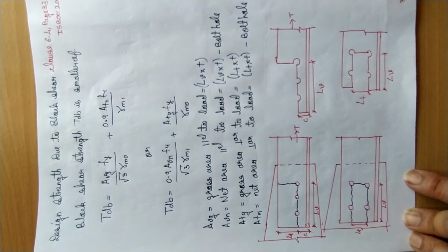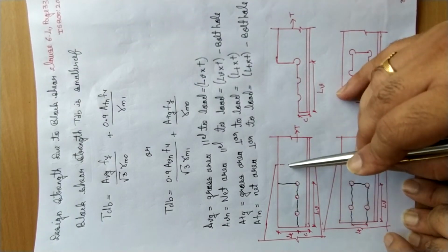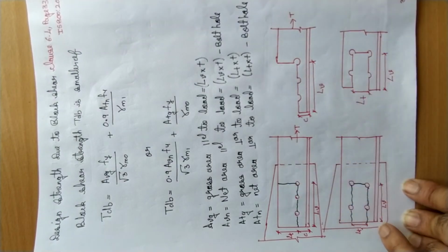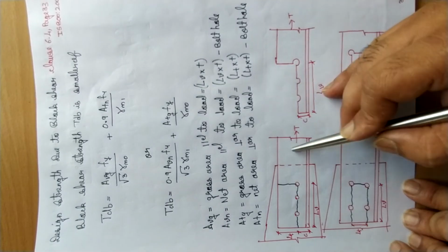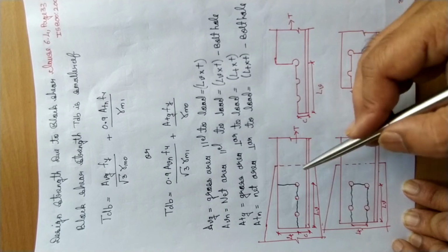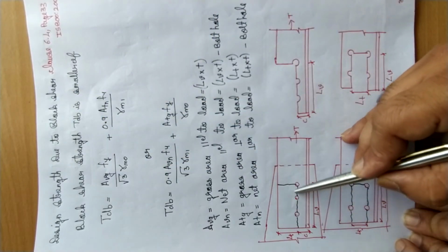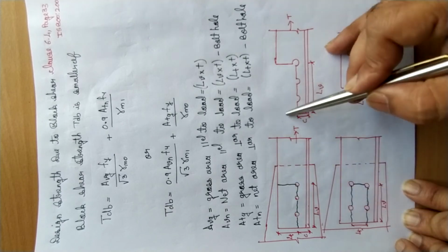Let us take an example. So I have taken an example. Let us take the first example. This is the angle connected and there are 3 bolting systems. So the force is acting here, tensile force. So it is pulling the angle. So how will it fail when it is in block shear? So 3 bolts will fail in this portion. You can see this will tear off.